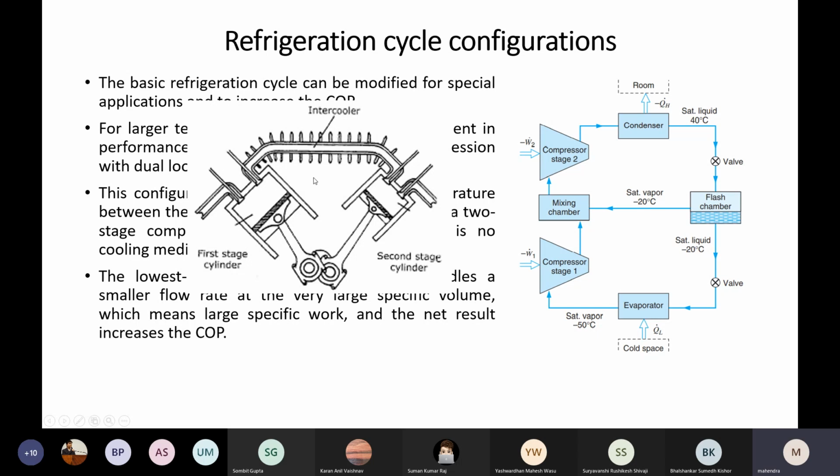If you observe one more thing, behind this setup, there is one fan also. That fan is also run by the motor. That fan sucks the air from the environment and pushes it upon this entire system. That way, the air while reaching over here will be at 6 bar, but the temperature is relatively decreased from here to here.